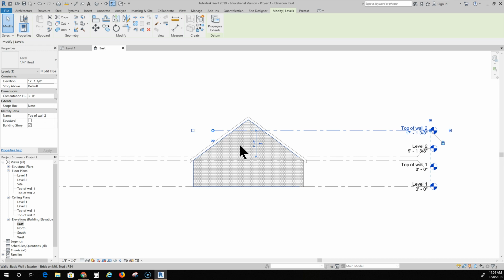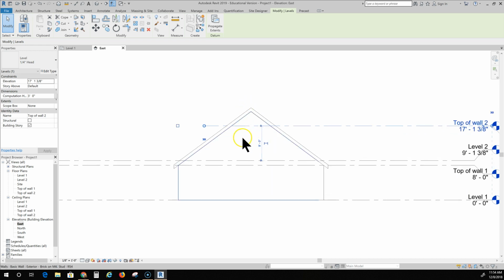And too, if this is going to be a finished area up in this portion of the house where the attic would normally be, you still need to have a window for means of egress. So a dormer makes a perfect addition to accomplish that. And of course today we have air conditioning, so we're not too worried about the air circulation, but we do want a window for natural light and that means of egress.